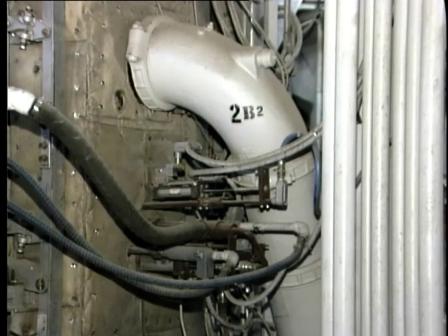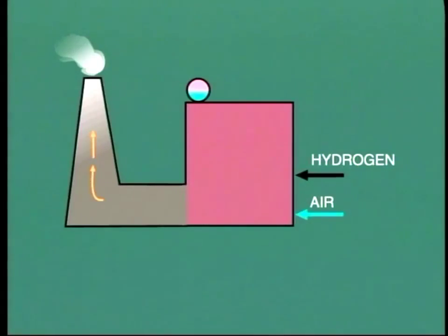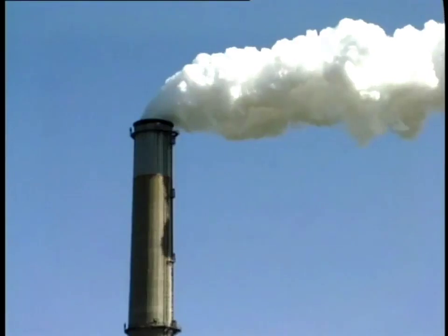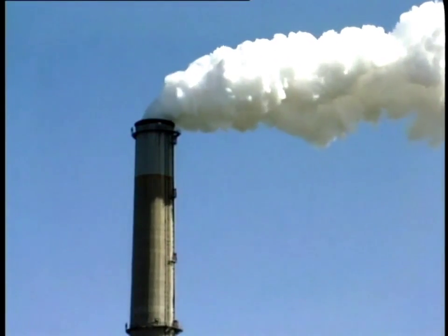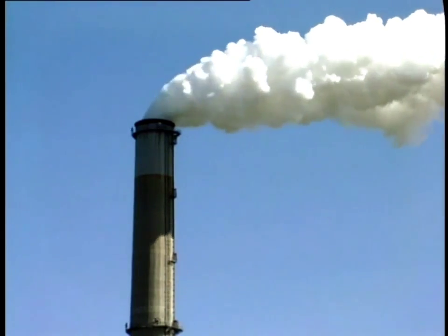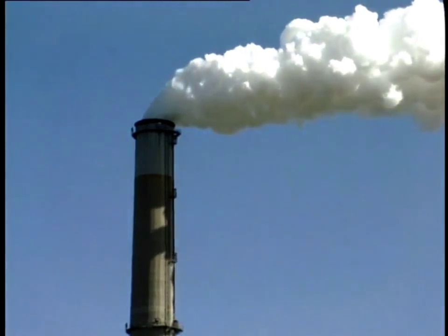And we'll be looking at this in the next segment. Before getting into that, however, we must look at one more important item, and that is the effect of moisture in the flue gas. We have already seen that the combustion of hydrogen releases a lot of heat and also produces water vapor. In the example studied, this came to 0.855 pounds of water for each pound of fuel oil burned. As we pointed out, this water is in the form of vapor as it passes on through the boiler and out the chimney to atmosphere.